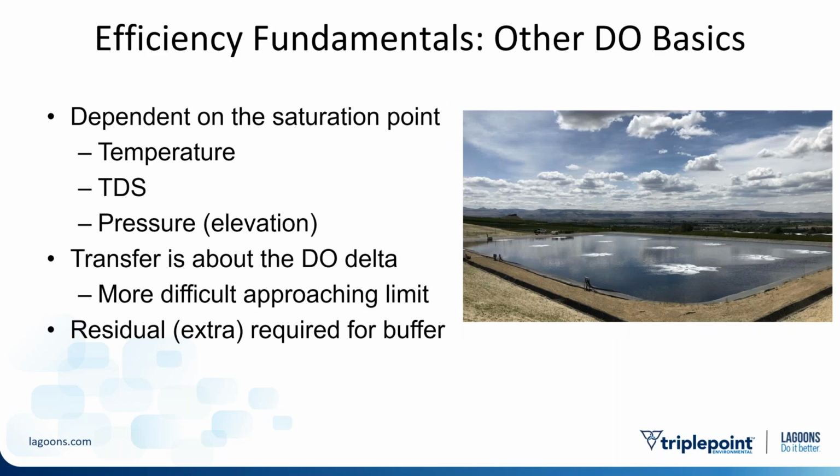And there's a few other DO basics that we should discuss. Dissolved oxygen is dependent on the saturation point of oxygen. So it's easier to transfer oxygen in the middle of winter, where the saturation point might be 14, than it is to transfer oxygen in the dead of summer, where the saturation point might be 9. Total dissolved solids also affect dissolved oxygen transfer, and pressure definitely affects oxygen transfer. Again, the more pressure there is in the air, the easier the air can transfer oxygen to the water.